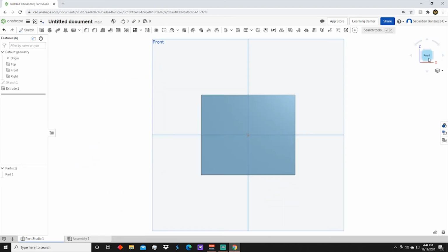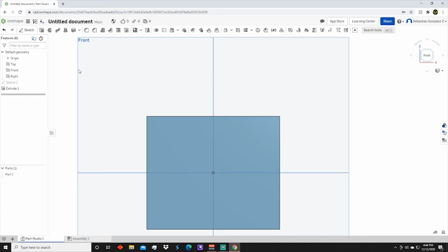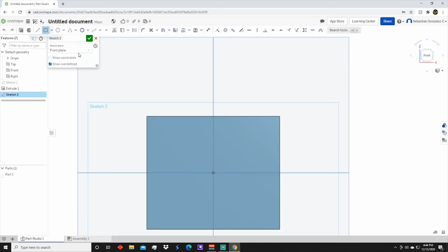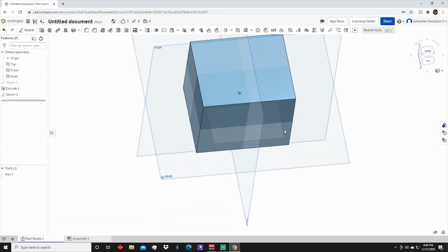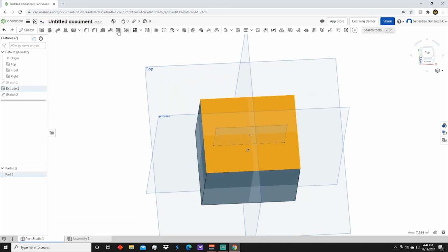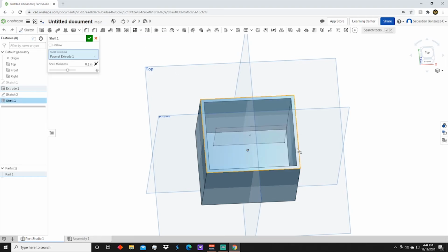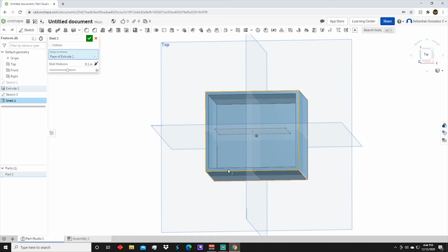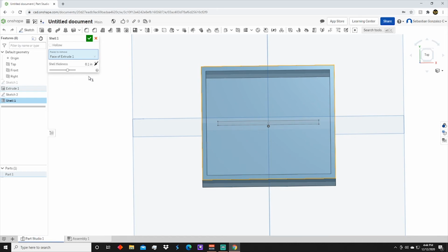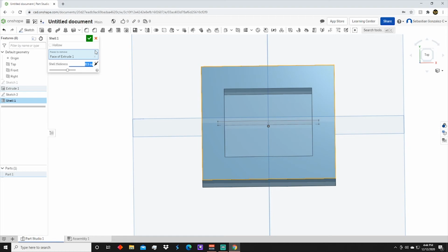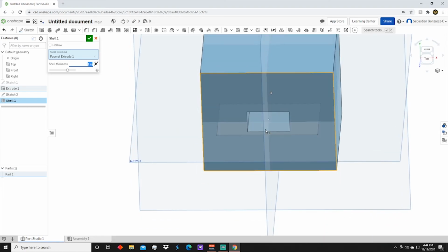Ribs. The easiest way to explain it would be a rib cage. So I'm just gonna do a little sketch right here, because that'll let me use ribs properly. But first, before I use ribs, God, that sounds so weird just saying I'm gonna use a rib. Shells, pretty important. Just lets you hollow out the shape, and the shell thickness is the thickness of this. So if you want to make the amount hollowed out smaller, just increase that number.